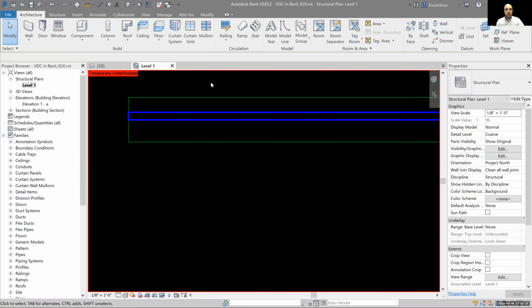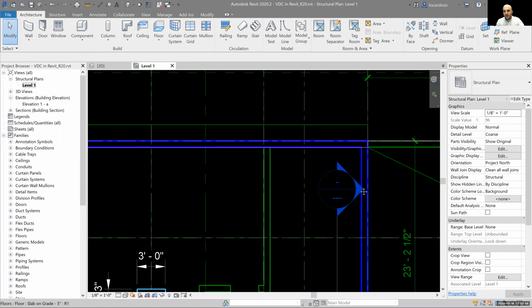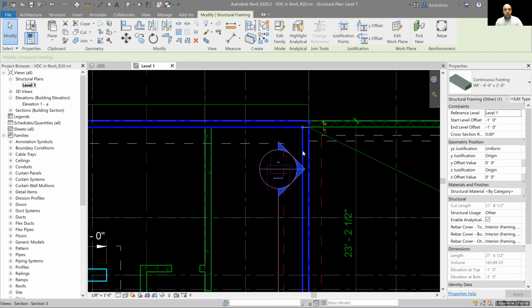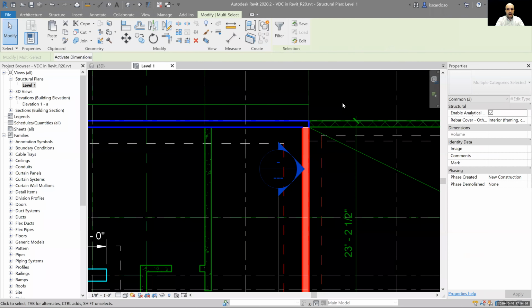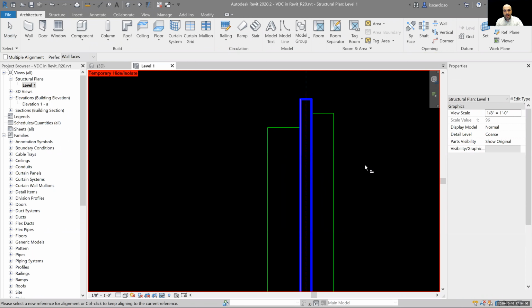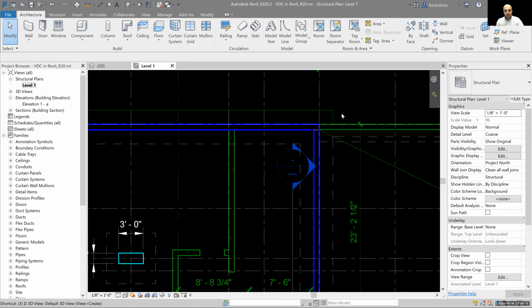Now after I'm here is where I can do an align, AL, center of wall, and you can see that it doesn't matter where on this beam I highlight, it'll automatically assume I'm going to the center. I'll click on center. And same thing on the other side. So this is what I mean by having many workflows in here, because I don't want to add a beam, right, or add a foundation element. Let me restore my view. And now let's go to 3D.